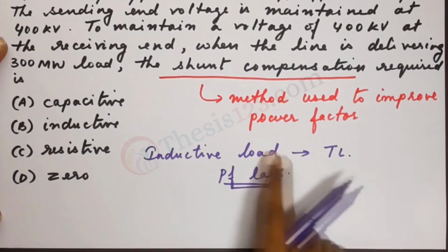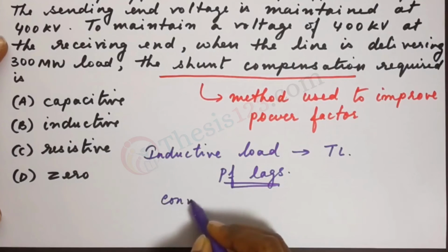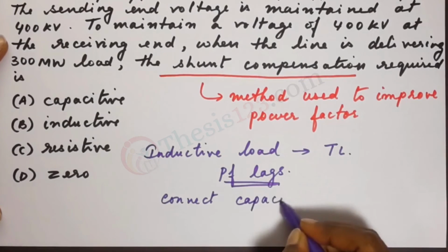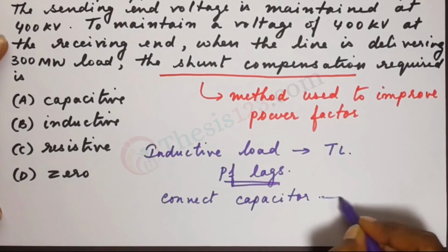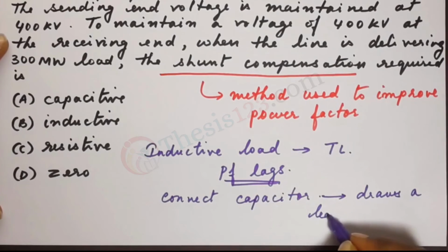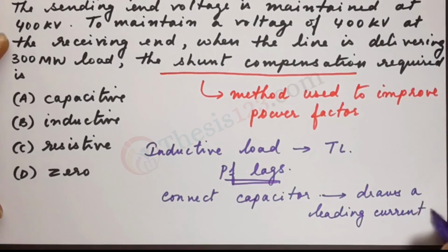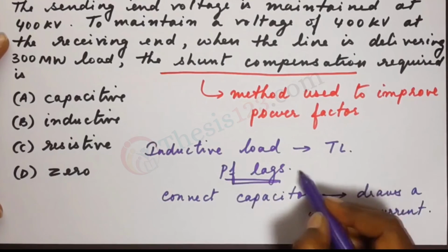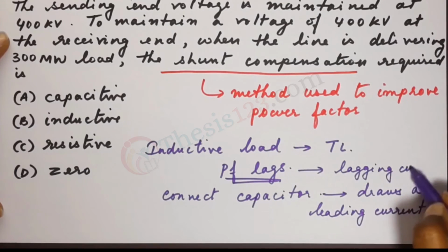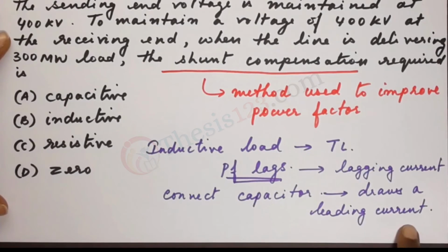And in order to compensate this lagging power factor, we connect a capacitor, which draws a leading current.